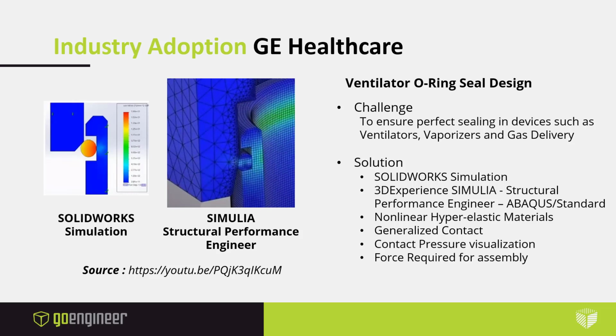So they decided they required two different success criteria to validate a design. One was to study the contact pressure, which they could using the contact pressure visualization tools, and the next is deriving the force required to complete this assembly, so that this assembly forms the seal and also doesn't take too much effort to assemble.